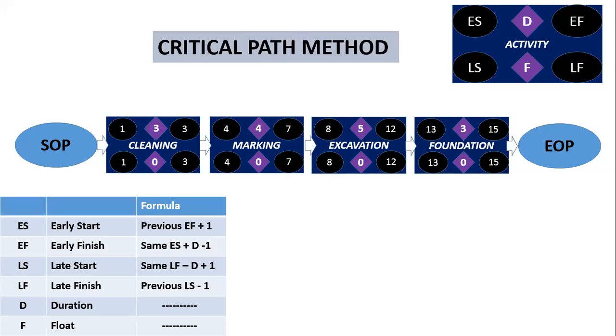Next we are moving to the excavation part. What is the early finish of the previous activity? 7. Then what will be the early start of excavation? 7 plus 1, 8. Then what will be the early finish of excavation? 8 plus 5 is 13, minus 1, that is the 12th day. We are completing the excavation part on the 12th day of the sequence. Is it or not?